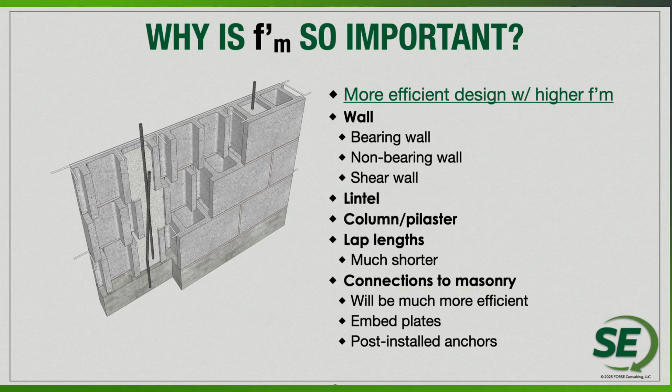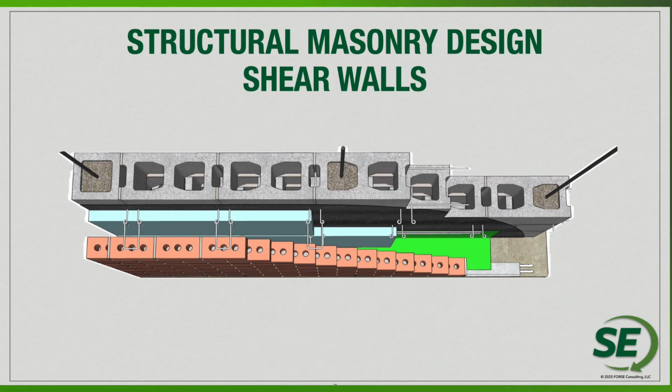So f'm, why is it so important? There are a lot of different reasons, but making sure that we have an efficient and effective shear wall design is certainly going to be one of the many reasons why we need to understand and utilize the appropriate f'm strength of masonry for our project.